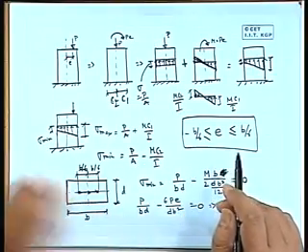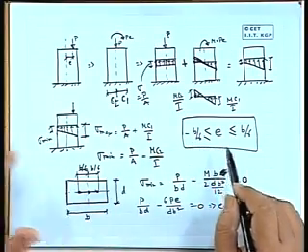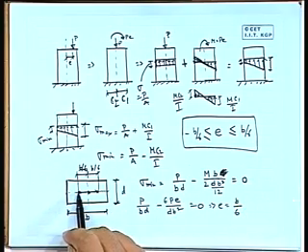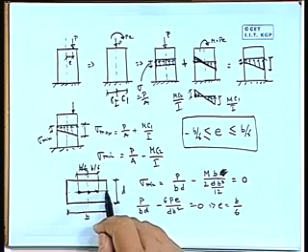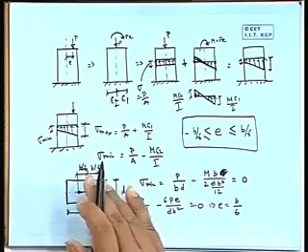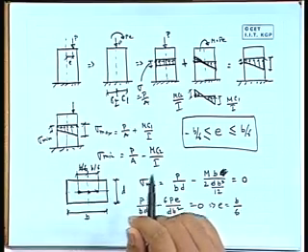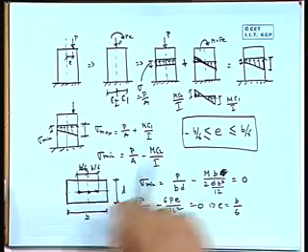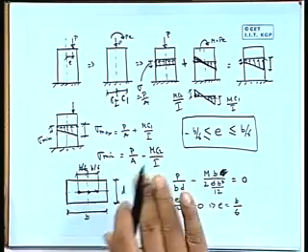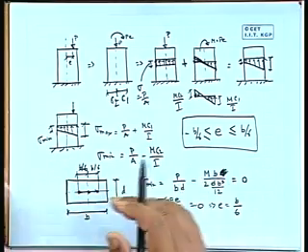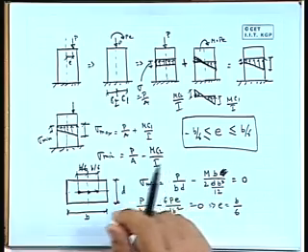So, that problem if we put in the reverse manner. If it is on the minus side, so if it is at minus B by 6, here stress will be 0 and from there it will generate. So, there it will be a triangular stress. If it is here at B by 6, it will be a triangular stress. If it is less than that, it will be some value, it will be a trapezoidal type of stress block.